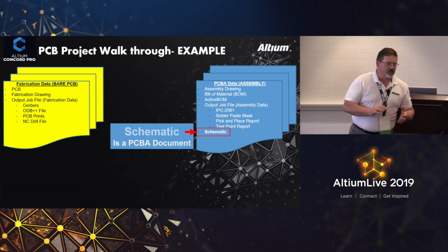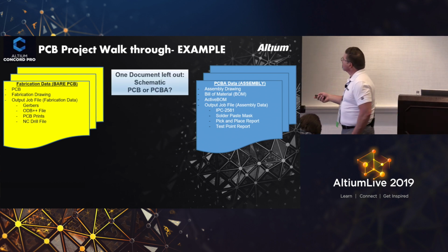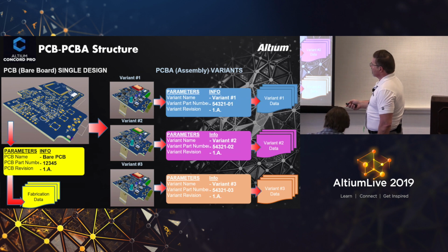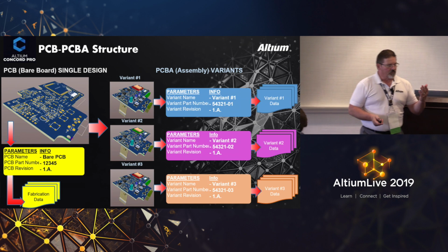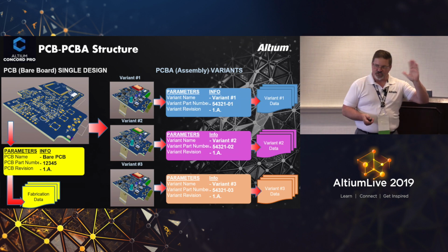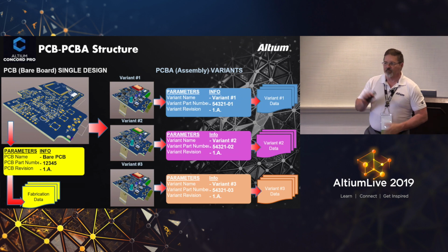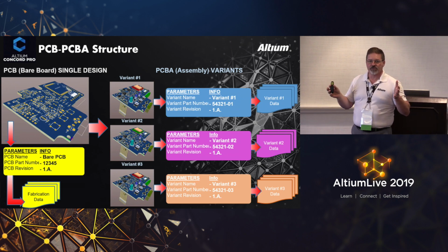But we bump that major revision. We bump what was back here, this 1A, okay? The PCB revision, the major value, which is your 1, and your minor, which is your A. We will bump the A for anything that does not impact the Gerbers.